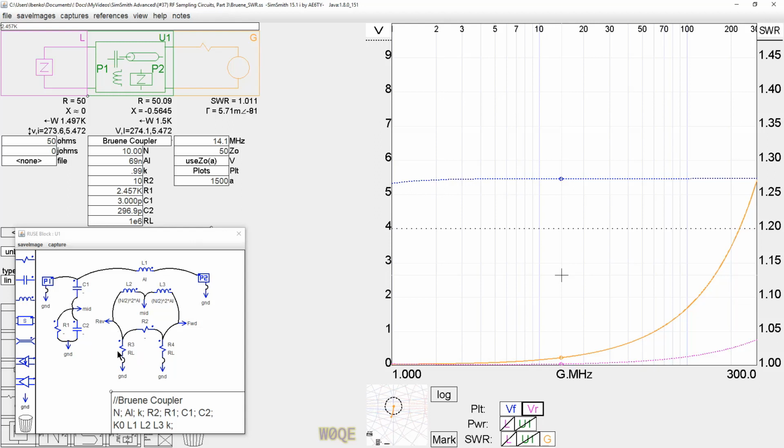I find that these resistors, though, unfortunately have to be very, very high. Look what happens. They're set at 1 megaohm right now. Look what happens as we drop the resistance values down. As we start to drop them down to something that's even halfway close to being something we could drive 50 ohms with, the low frequency end of this just goes away. If we want to drive 50 ohms with these resistors, we have to have so much attenuation that what's left is a coupling factor of maybe minus 60 dB or so, which makes this circuit not very useful.